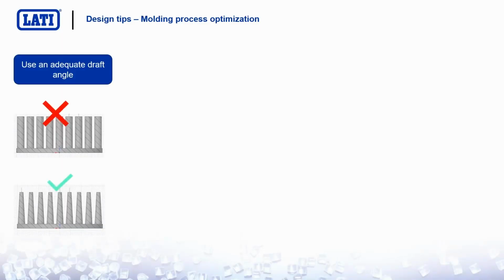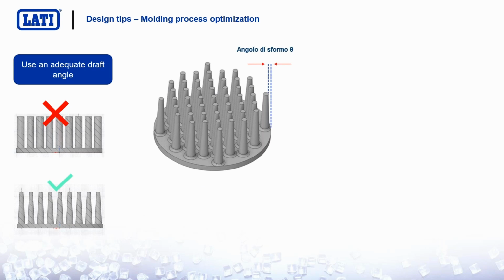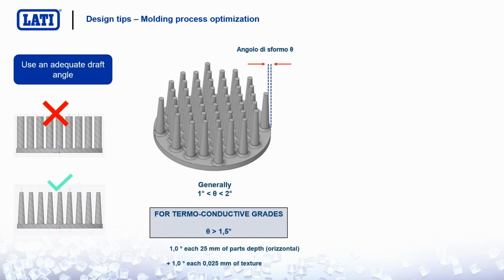Then another important tip is to use adequate draft angles. This is because these materials are heavily charged, filled with conductive fillers, and may result a bit brittle and feature quite low strain at break. So there might be some problems during extraction.